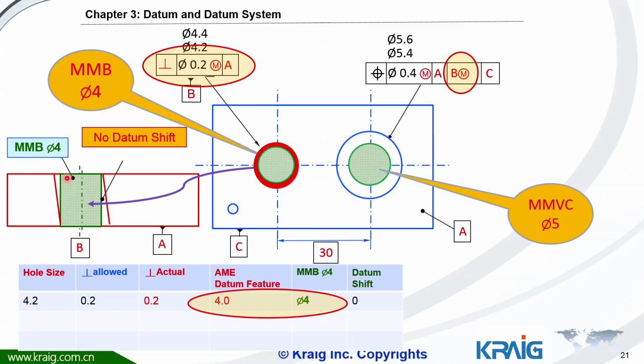However, if we push the M4 bolt inside, then there's no room to deviate, to shift, to displace, to adjust, right? Because the hole is tilted. So you cannot adjust this part anymore.